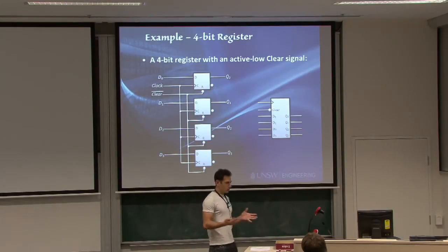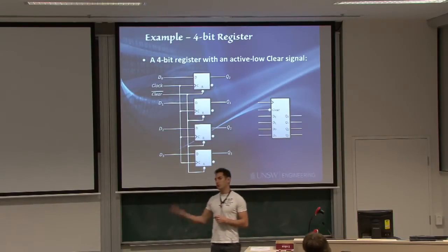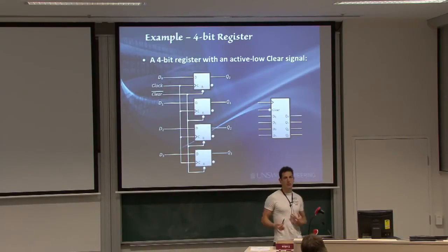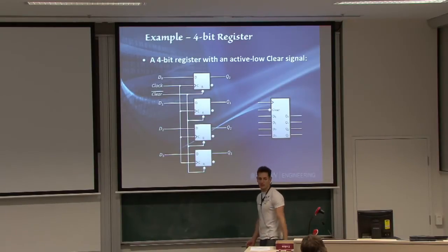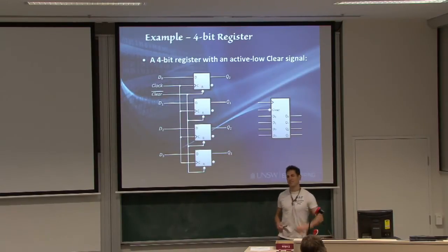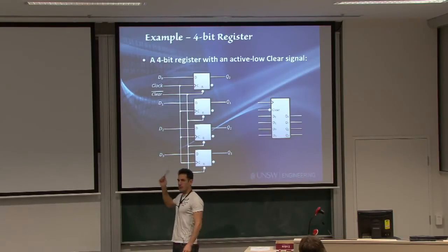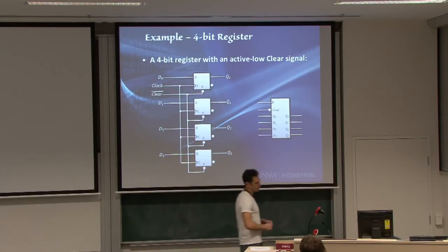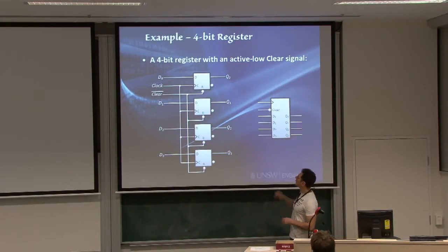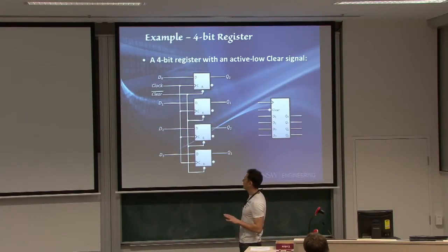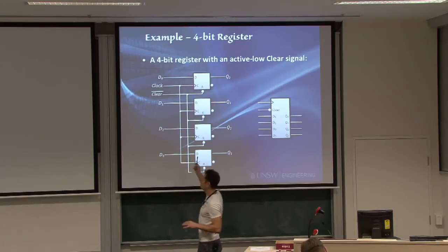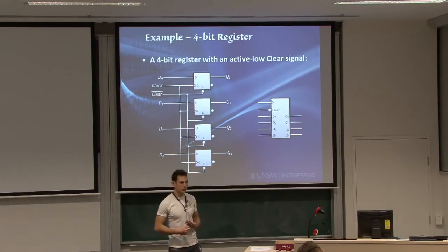Now, computers and other digital systems usually have some master clocking signal that will keep clocking the entire system at some rate. You know, the latest Intel Pentium Centrino i7 thing is 3 gigs maybe, I don't know. Which is obviously not the rate that we want to store new information into this flip-flop. But we don't have any way with this register to tell it, just hold on to the value that you have already without loading a new signal on the next rising edge of the clock.